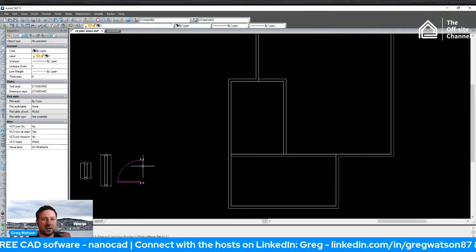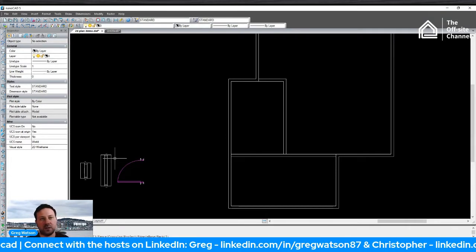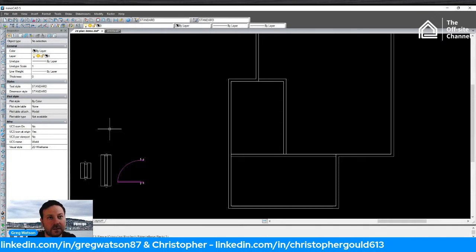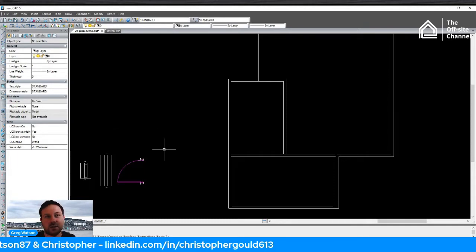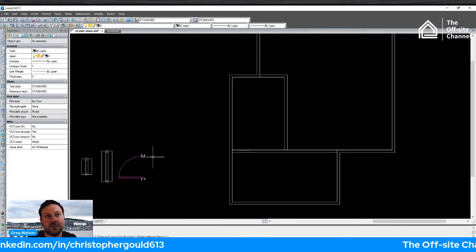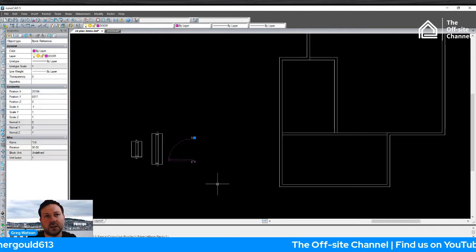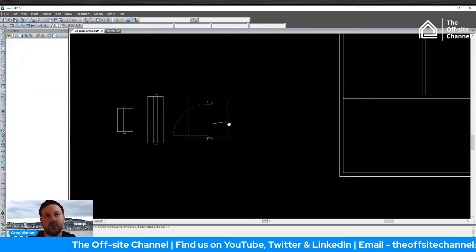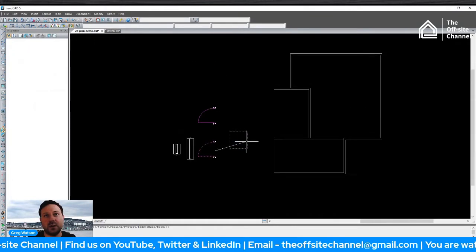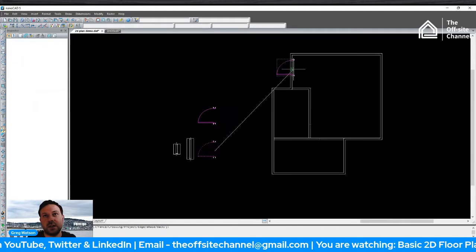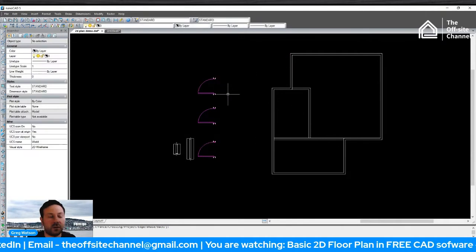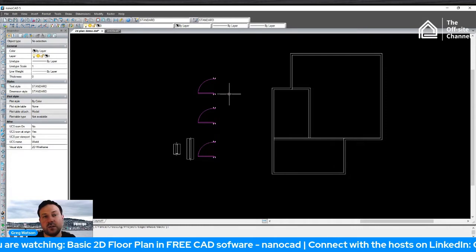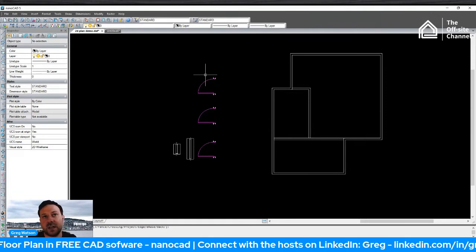Now, I do have these doors and windows here predefined for these. I assume that you probably have something similar with all your external joinery, etc., etc. So just for these, I have done that. And so what we can do is let's take this here and let's right click and move and copy. Let's do one here. So we're going to need a door for here, and an external door here. I'm not going to have external doors in the model that I do have all this stuff saved, but for ease again, I'm just going to use this internal door set.